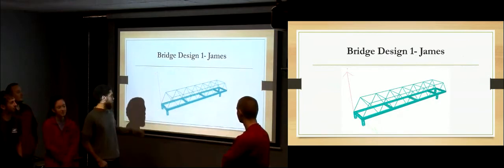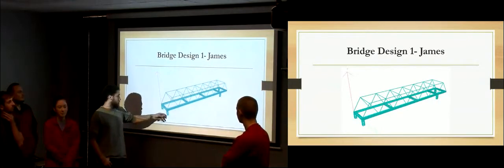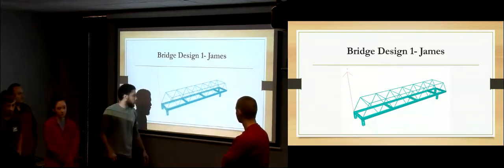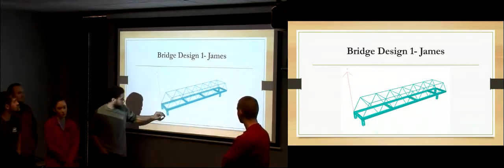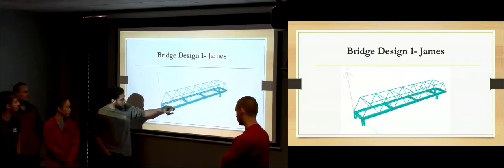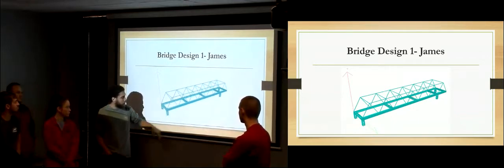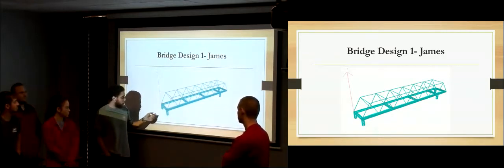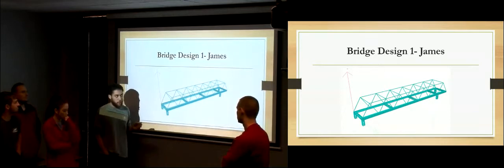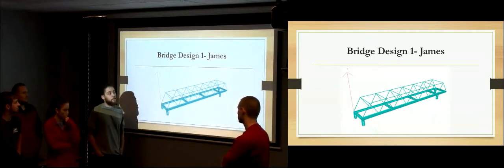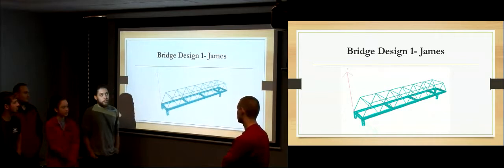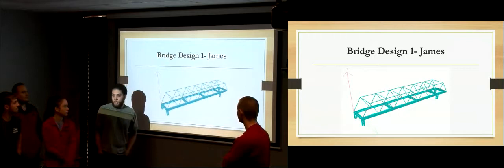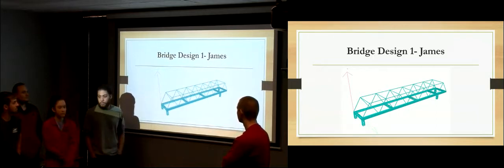So my initial design was just a simple truss on rectangle prism members for the stringers, the cross members, and for the footings. And I had secondary bars in between all the rectangular prism members, but the stringers didn't really meet the specs exactly, and the deflection was a little bit too high, and it weighed 676 pounds with 80 connections, and it took like 45 minutes to build. But it was just not the best design, so we didn't end up picking it.